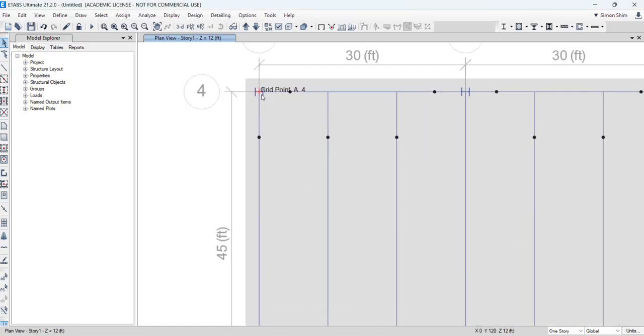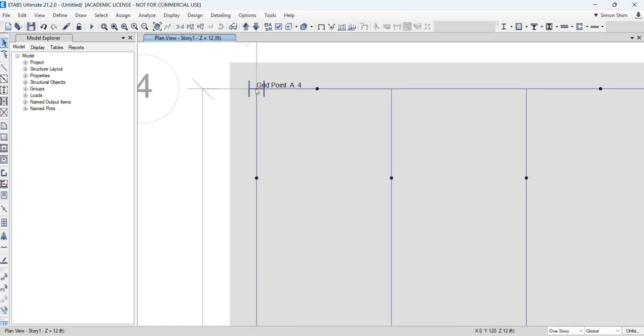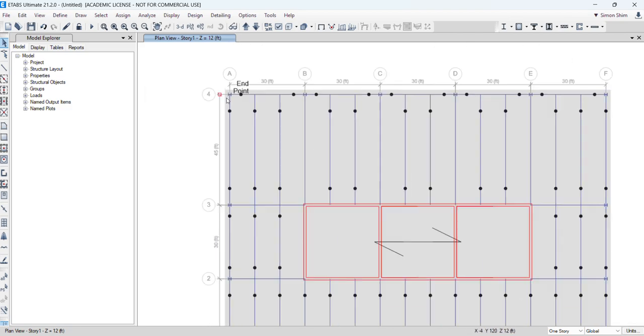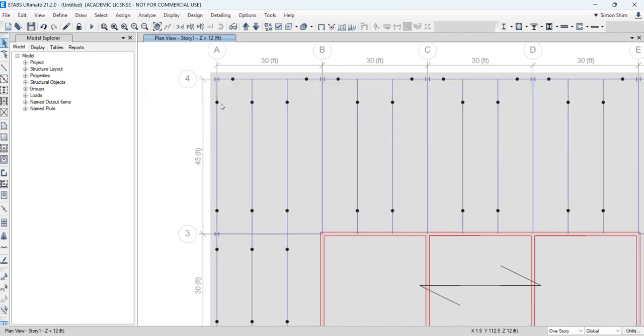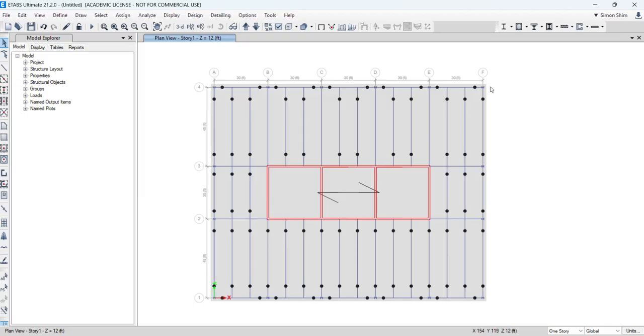So you see that initially we drew the slab by picking the intersection points of the corners, but I just expanded this plate by 24 inches. So this is the expansion, the overhang. Eventually in a real building, we need some slab overhang, so the exterior curtain wall will be attached around this overhang slab. All right, so we just completed the geometry.